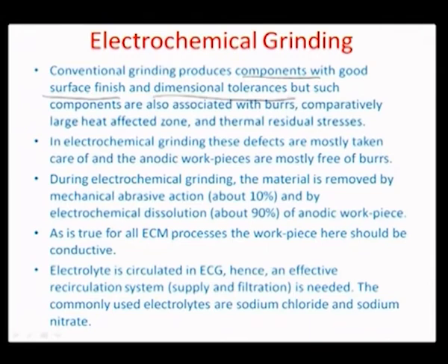But the dimensional tolerance gets significantly affected with associated problems like burrs, or a comparatively large heat affected zone, or thermal residual stresses, which would create a sort of breakdown of the surface structure, because grinding is a multiple cutting tool with a lot of abrasive particles embedded onto a matrix which rotates with respect to a workpiece, and there is a heavy amount of plastic deformation on the surface, which happens because of the small abrasive grains continually hitting the surface at a very small depth of cut.